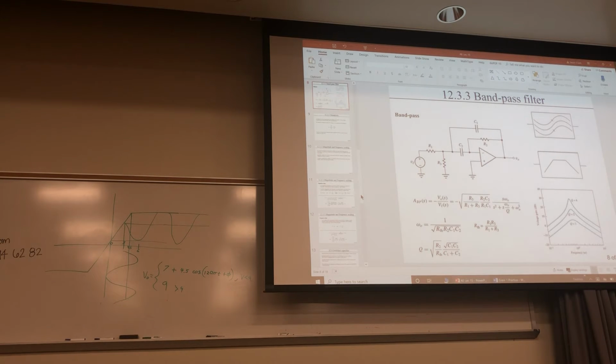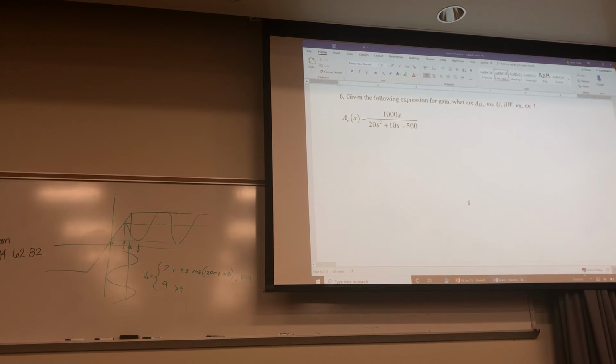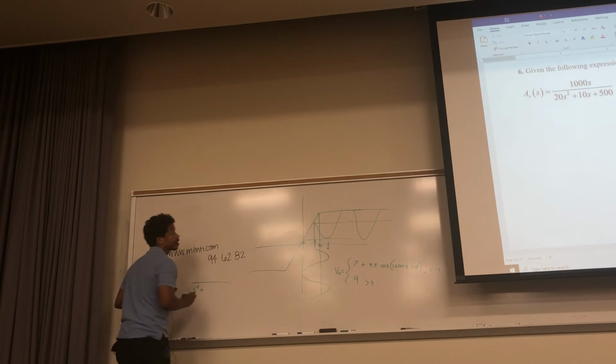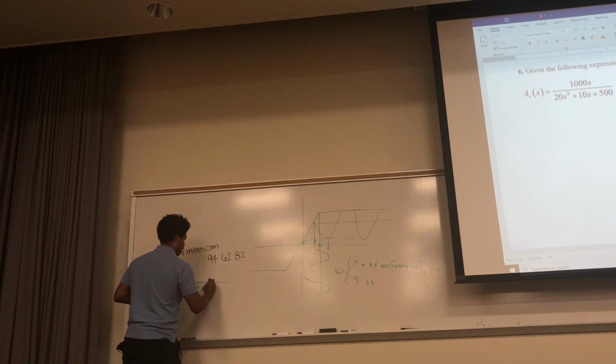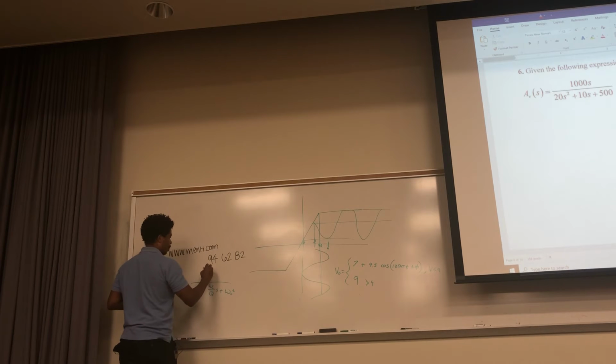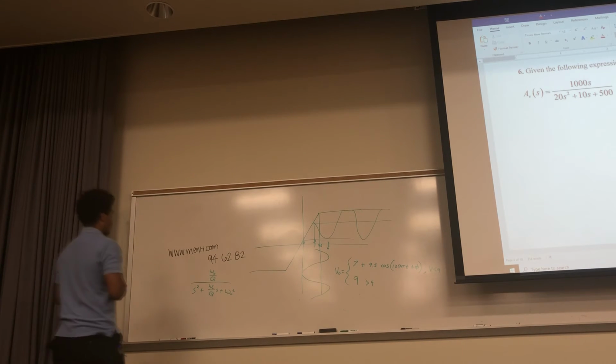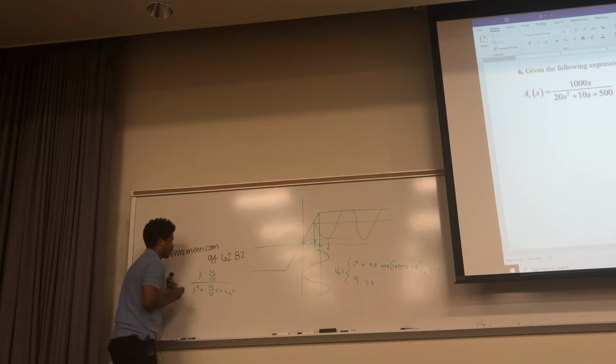So there are different forms of bandpass. For this one right here, we're looking at this form where we have s squared plus omega 0 over q s plus omega 0 squared, and on top we just have omega 0 over q s. Oh yeah, well I guess you do have this. You can have this factor in front too. Yes.